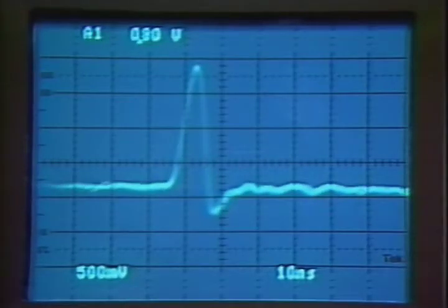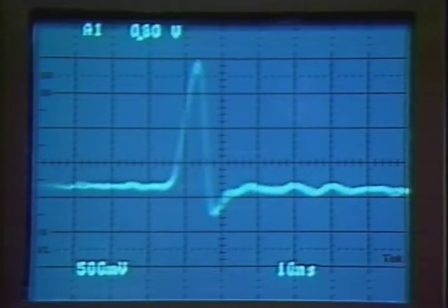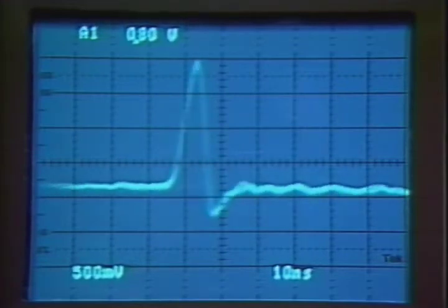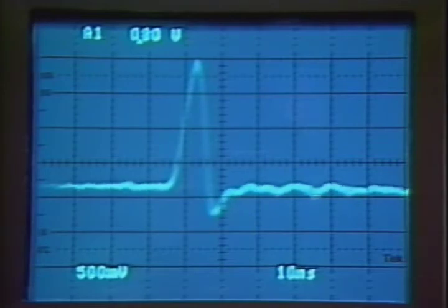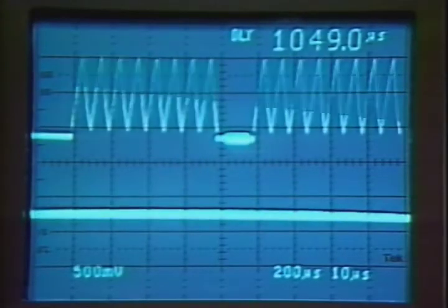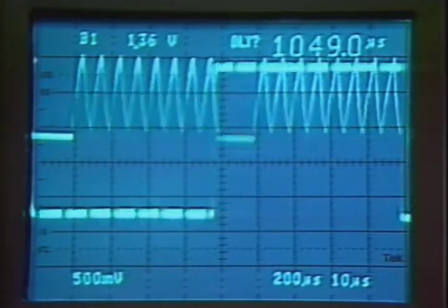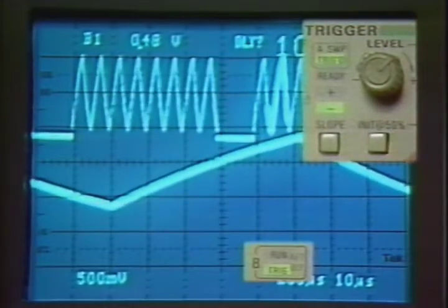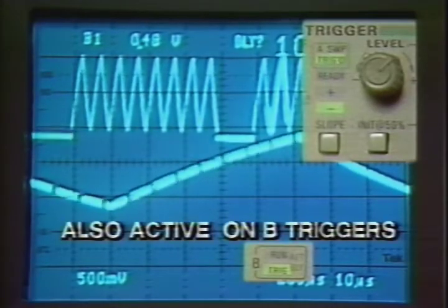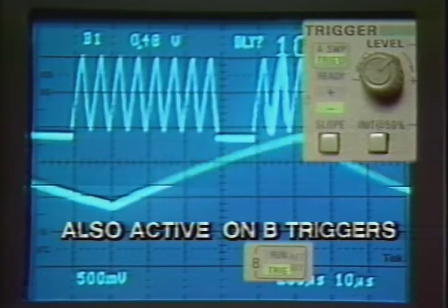The scope also automatically moves the readout characters around to new phosphor areas each time a control is changed to avoid aging those spots. There are some new functions in the 2467. One is a 50% trigger level selector button. This function auto-level triggers a waveform at 50% amplitude, as if the trigger level control were centered and an auto-level sequence was initiated. It just does it faster.